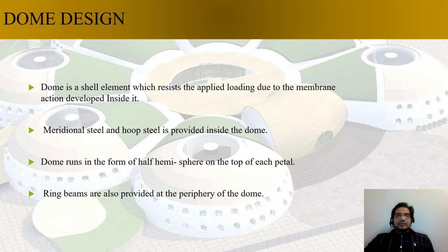So the dome that I was discussing just previously is actually a shell element, which takes the applied load due to the membrane action developed inside it. Whenever you apply a load on any kind of dome structure, consider you have a cricket ball or a tennis ball, just try to apply pressure from the side, so it will try to distribute the load into all sides, into all directions, I should say. So it's a kind of membrane action that helps to distribute the loadings.